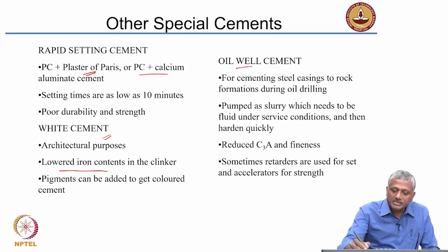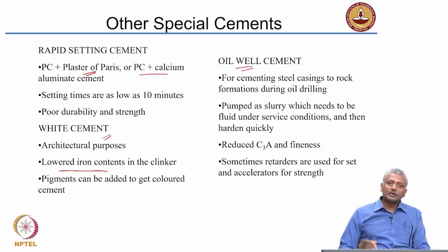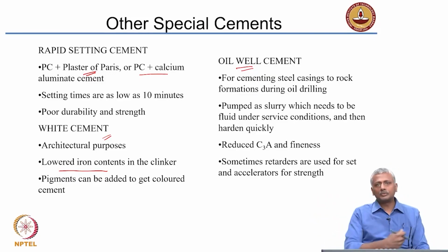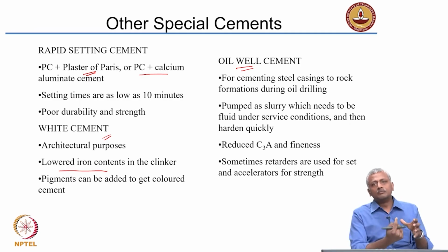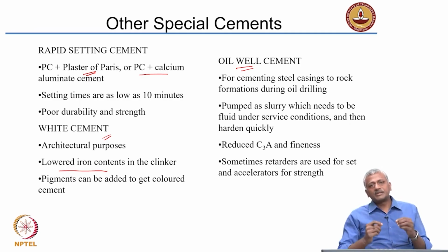Then there are other special cements like oil well cements which are used for oil well drilling applications. So, when you drill very long bores into the rock to extract oil, to prevent the soil from collapsing, you need to line the walls of the bore that you have dug with cement.